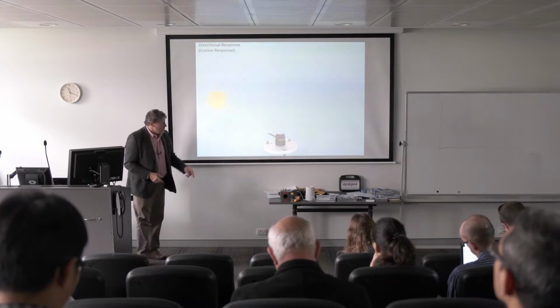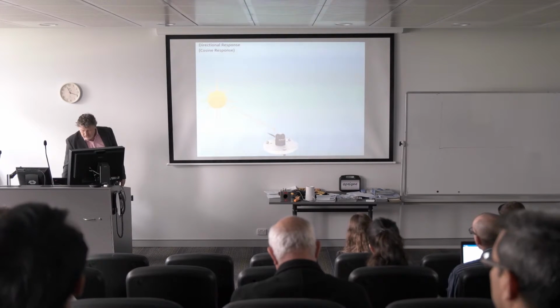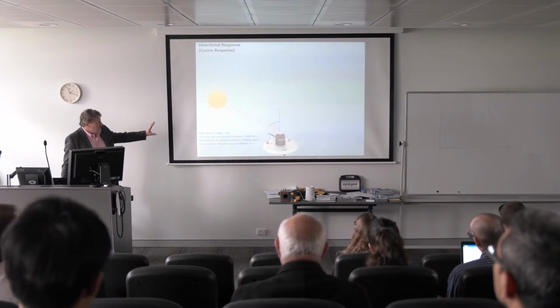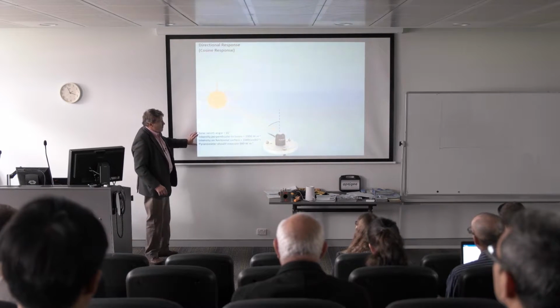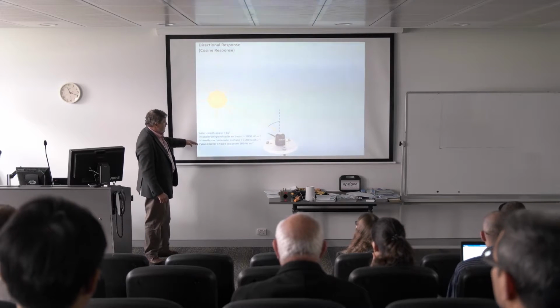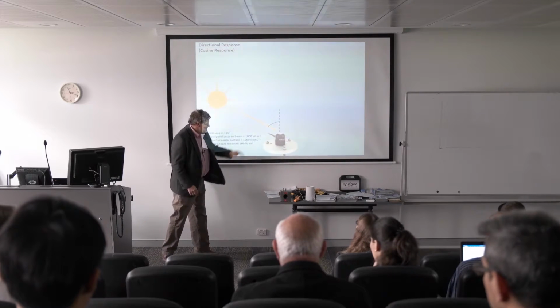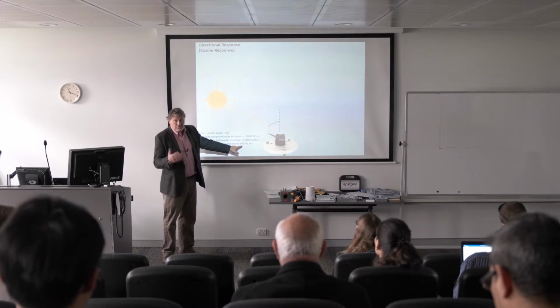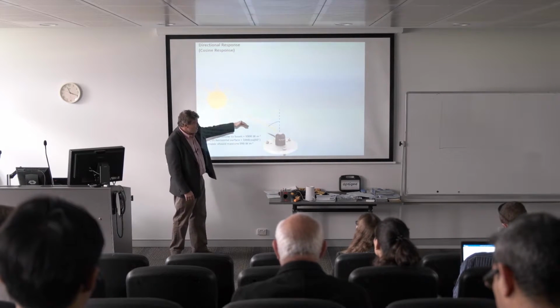So here's an example of low angle radiation coming into this, and that's why we call this cosine correction, because if it's coming in at this angle, the sensor should read 500. It's not supposed to read 1,000, that's cosine correction.